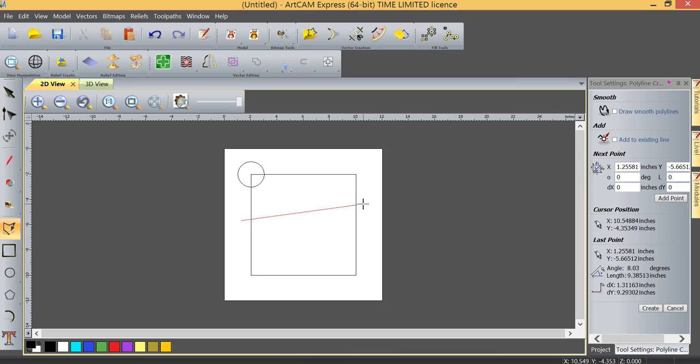Now, again, I mentioned earlier that when the cursor makes a change, then it's identifying that something is happening. And now I want you to watch as I move the cursor along. When I get to the horizontal plane, it changes from what you see here, this set of crosshairs, to basically the line with the circle through it. And that line with the circle through it is basically establishing that we are on the horizontal plane. So if I left mouse click, you'll see that it established the next point, which now created the straight line